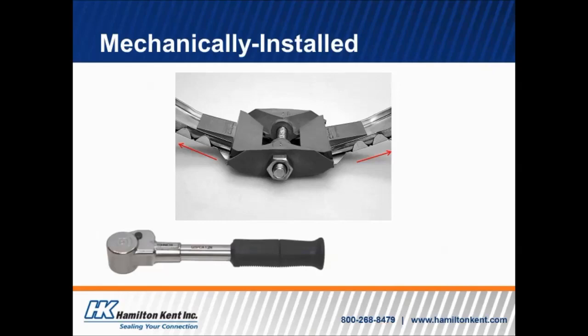What I mean by that is that if you have a contractor who has a pipe coming into the manhole at an angle he wasn't expecting, and he wants to make an adjustment to that boot, he can loosen that boot up, twist it a little bit so it meets with that pipe, and then tighten it back down. Well, what you're relying on him to do is, number one, put it back into that hole correctly so that it's going to seal well at the hole, but also that he's tightening it down enough to make sure that it's going to be tight. So there is some risk and reward to using a connector of this type, but it is the most popular type that we see.